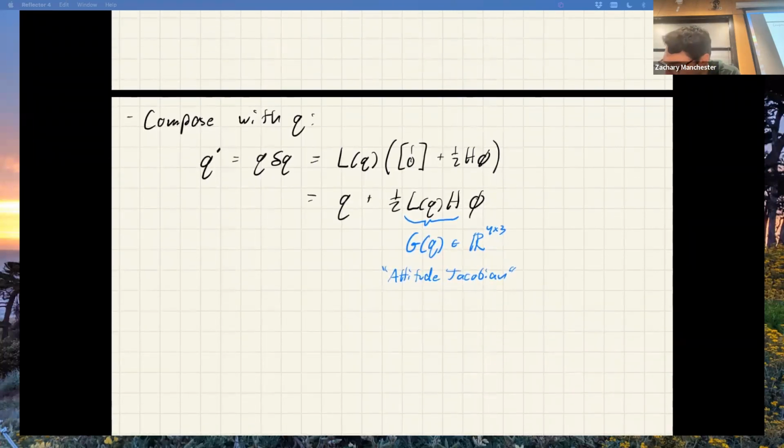There's one note before I get to the main punchline. Here I'm using this phi thing, and I told you it was an axis angle vector. Turns out it actually doesn't matter. You can interpret it as being axis angle, Euler angles, if you're evil, vector part of the quaternion, Gibbs vector, modified Rodrigues parameters. There's lots of these things, but it turns out that when I linearize the rotation stuff and do this 3-parameter thing, any 3-parameter rotation choice I make, whether it's axis angle, Euler angles, whatever, they all linearize the same up to some constant.